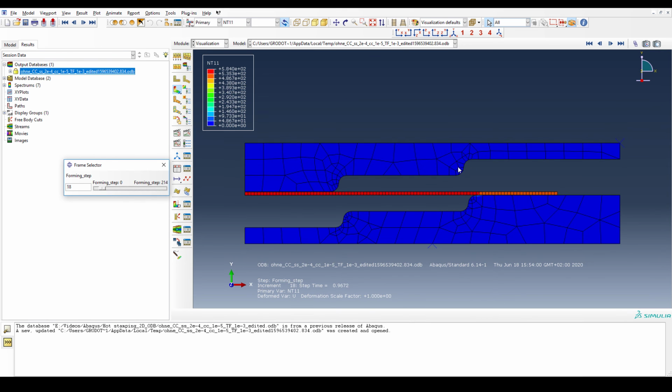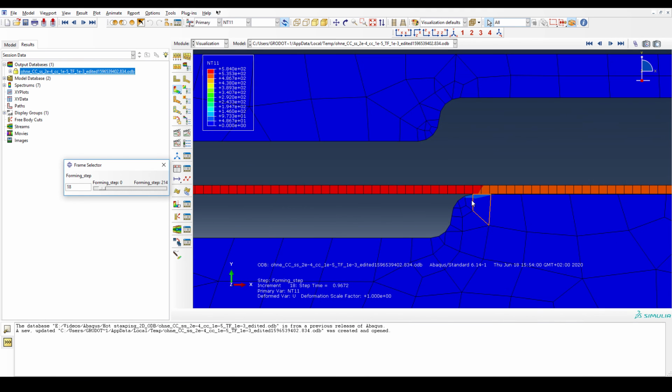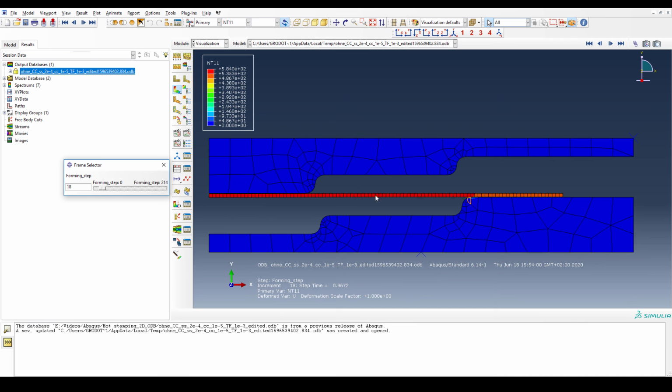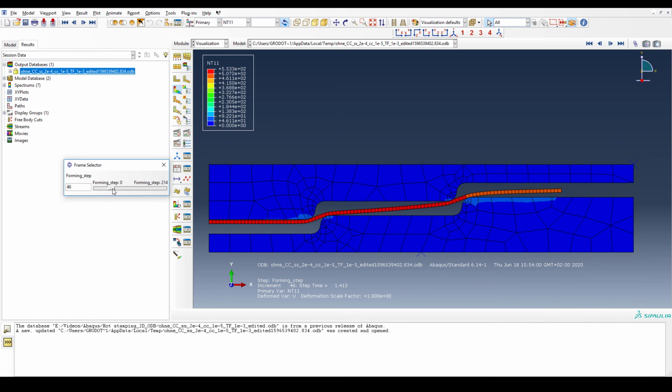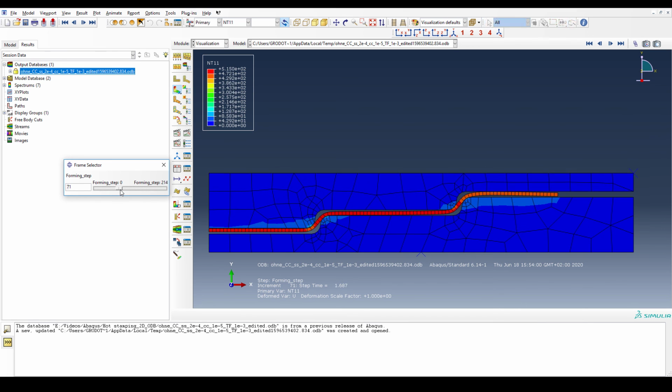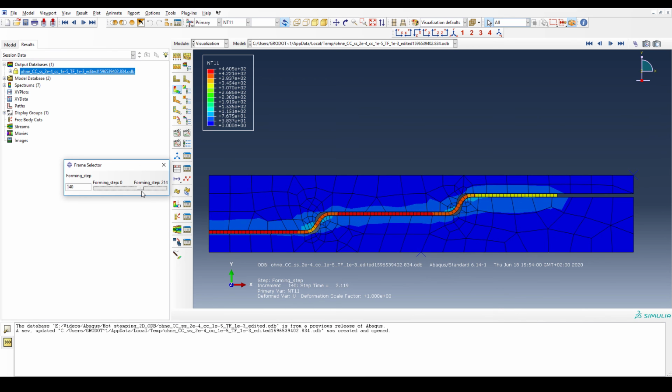And you see that in the area where it's in contact with the die, or almost in contact with the die, it loses more heat to the die, and this is where also the die heats up as compared to where it only sees the ambient. But you can see here on the maximum value, it lost in a second like 16 degrees C just by sitting there, which is what we expect the sheet to do. So this is pretty neat, and you can see how the heat is also transferred into the body.